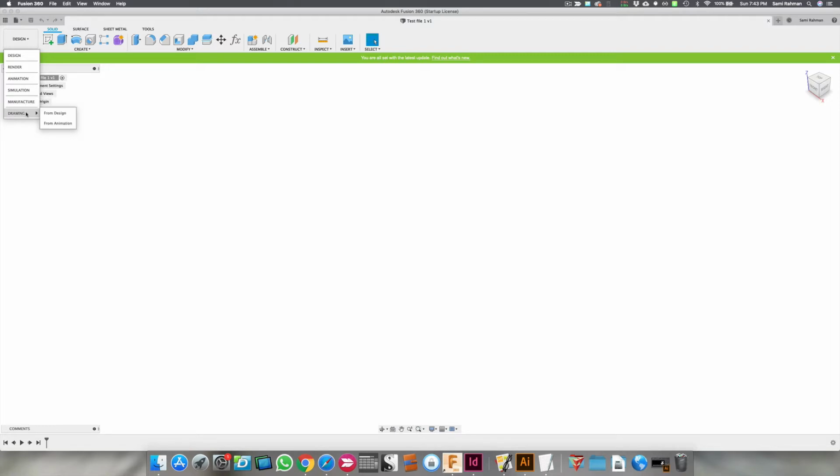And then there's also drawings. So traditionally, when you send parts out to be made, you give the company a set of master drawings, and that becomes the model. The model isn't the master. The drawings are the master. And the reason is that there's information in the drawing. You can point out information in a drawing, things that are important like tolerances, that you cannot do in a model. A model is just this absolute idea, whereas a drawing will have a representation of the absolute idea, but it'll also have all the detail, like how big a radius has to be,